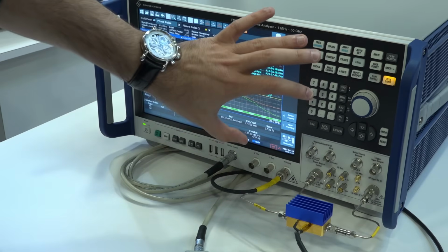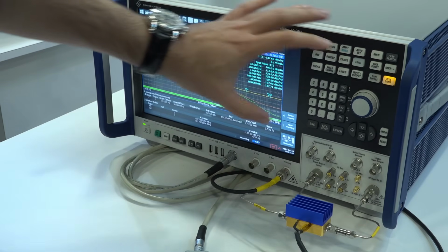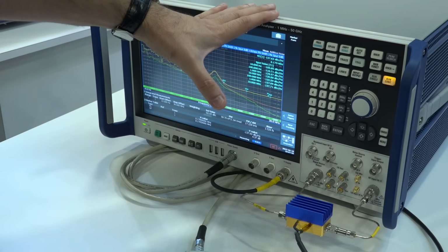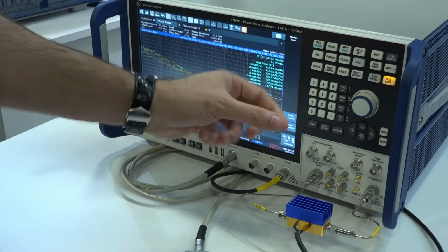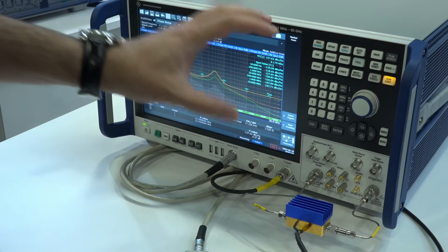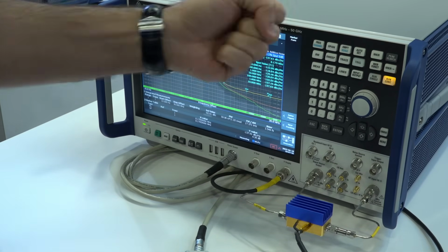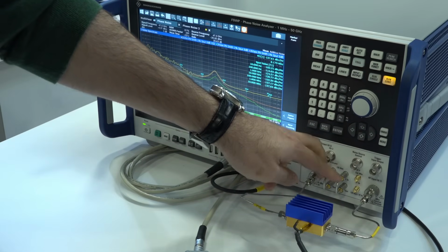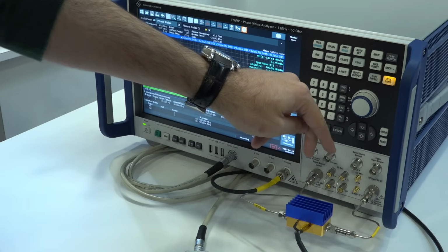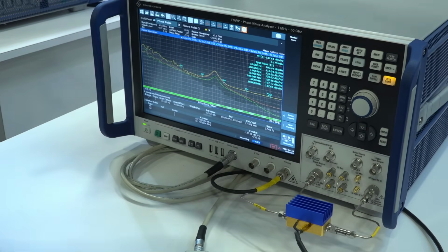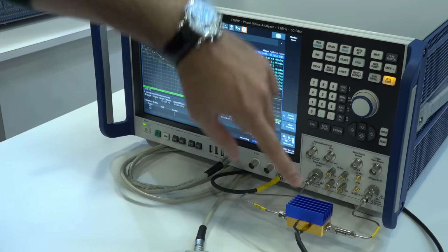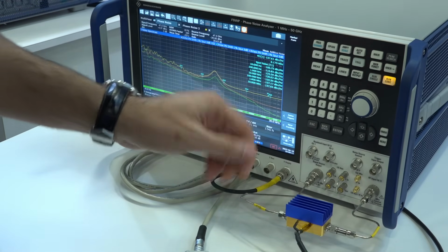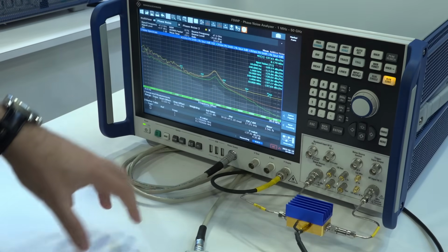Now, an internal source on this, let's say something like a 54 gigahertz synthesizer, is a very good synthesizer for a cross-correlation phase noise measurement system. But it's not going to be as good as a narrowband signal. So if you want to measure something that is a super high-quality cavity at very high frequencies, what you can do is remove these links, add your own dual sources into the instrument, and then have the control voltage of the instrument lock those sources to the internal one. Now you've got a locked external source that can be used for additive phase noise directly on the instrument itself.